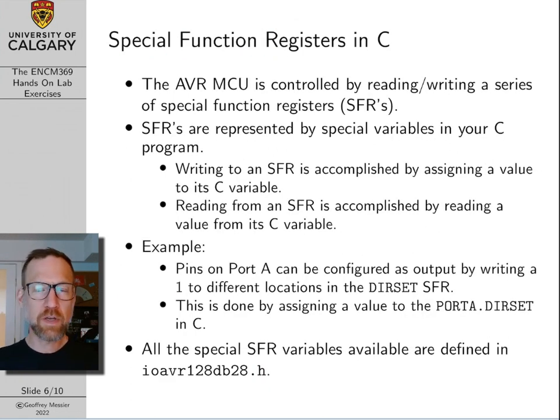So in this slide, I'm going to introduce the concept of what are known as special function registers, or SFRs. And I'll come back to this idea when I'm introducing Lab 1. But on the previous slide, I said, okay, the whole point of these labs is to learn how to use software to control the peripherals of the AVR chip. And you're like, okay, great. How exactly do I do that? Well, basically you do that by writing to and reading from special function registers, or SFRs.